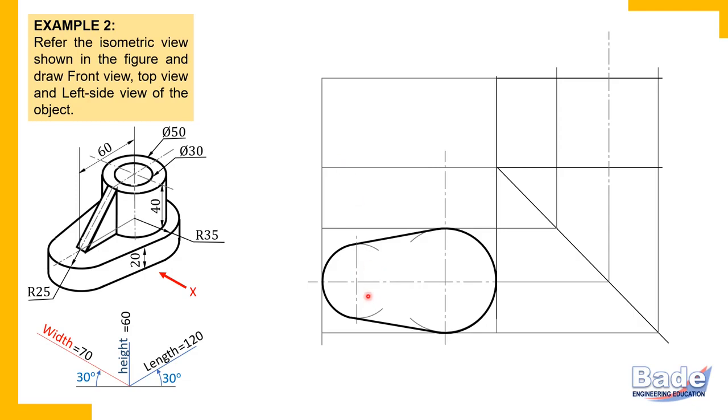So how to complete this plate? Try to understand. In a view of its shape, the remaining two views are rectangles. Use this logic. Remember, I have told you earlier that when you want to draw views of a machine part, it is placed in the first quadrant in its obvious position. What is that? Its major surfaces are parallel to one of the reference planes.